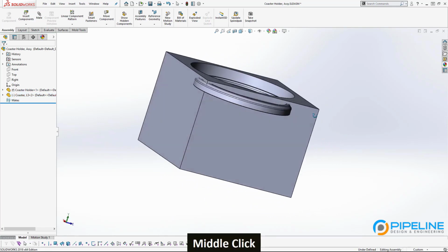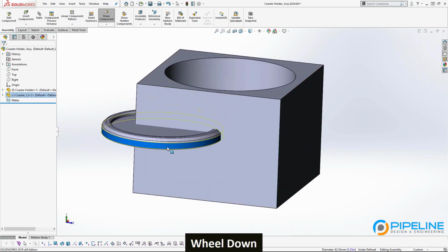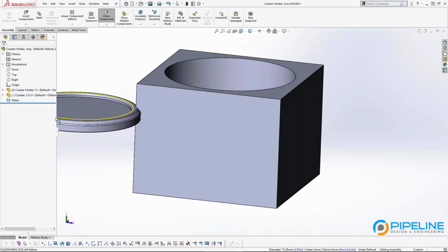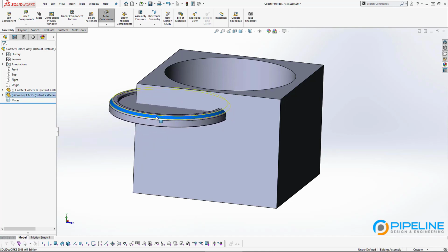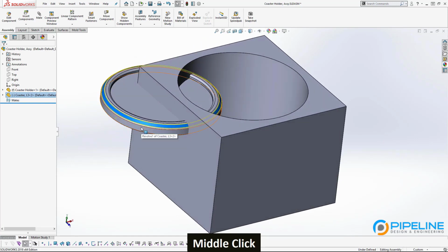So as you can see here, SolidWorks doesn't do a great job of detecting interference between parts. In newer versions of SolidWorks, I think starting with 2019, there's a feature that will allow you to kind of like bump these parts into each other. But in general, SolidWorks isn't quite sure what you're trying to do. So it's not going to tell you, no, you can't put the part intersecting with the other part, because maybe you are trying to do that. There are some cases where you will do something like this. And so SolidWorks certainly isn't going to tell you that it knows more than you do.